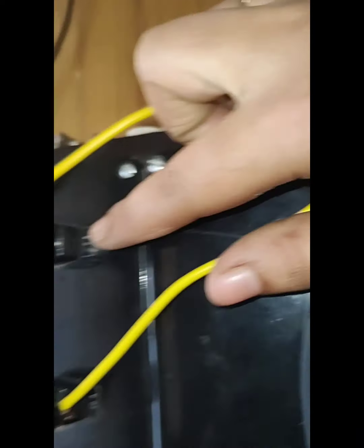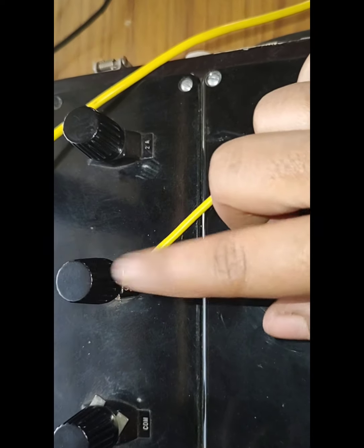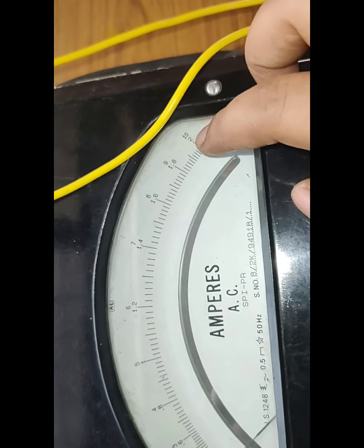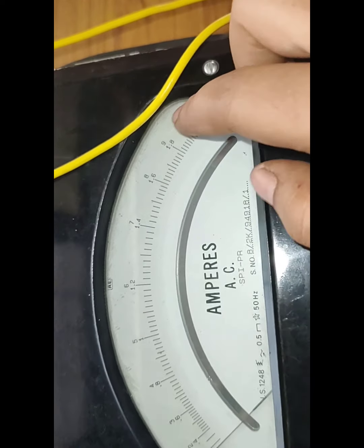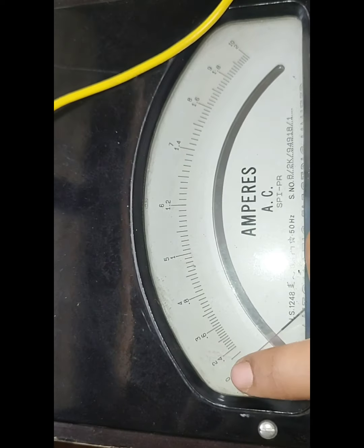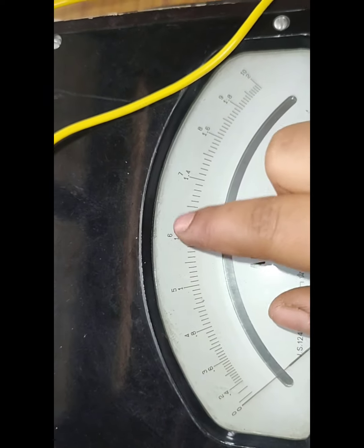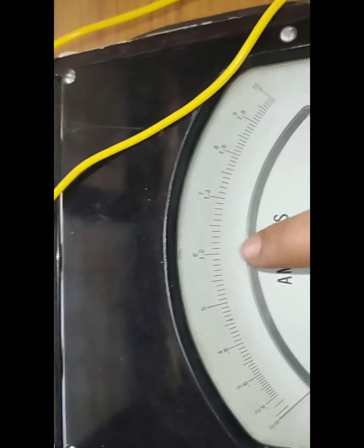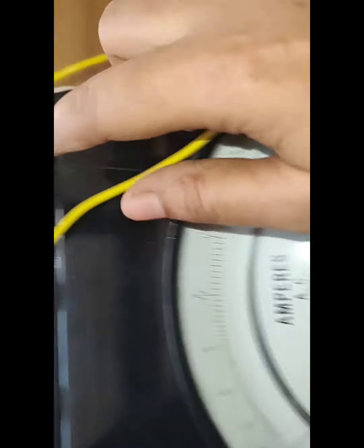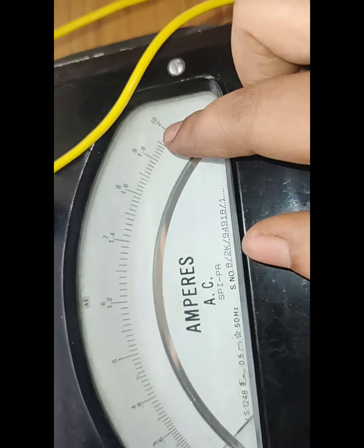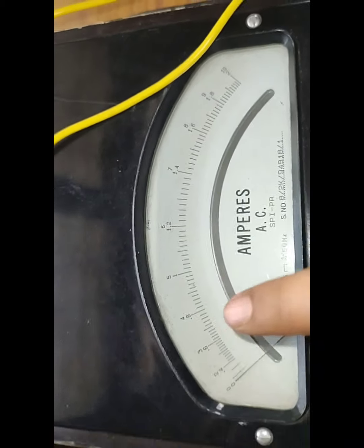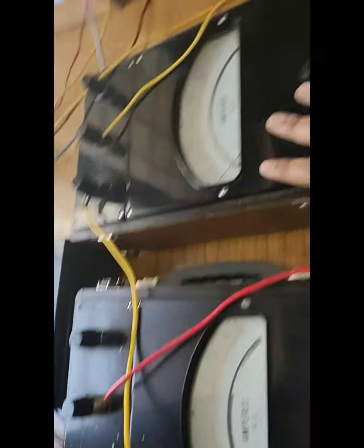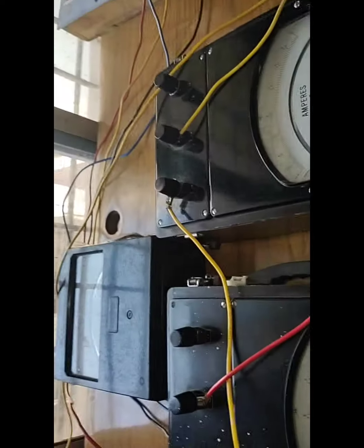There is a 2 amps range and a 10 amps range, and we have connected for 10 amps. So which one should we see? Below is 2 amps, above is 10 amps. So we should see the above one, that is 0, 2, 3, 4, 5, 6, 7, 8, 9, 10. We should take the reading of the ammeter range we have connected. If we have connected for 2 amps, then we should take the below readings. So first switch on the supply, set the voltage between two phases, and next apply the load and take the readings.